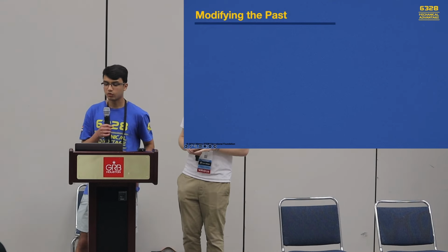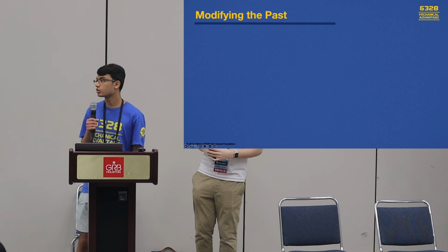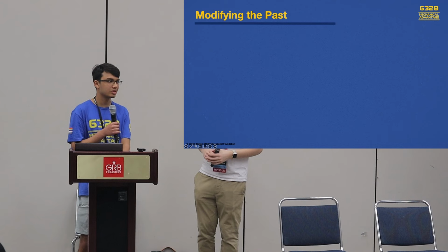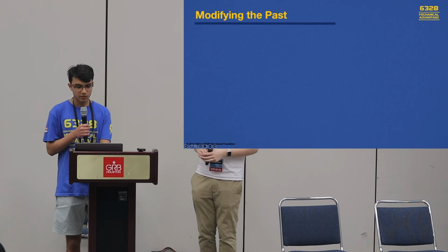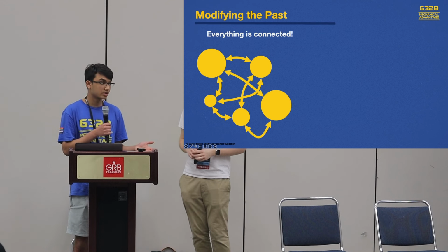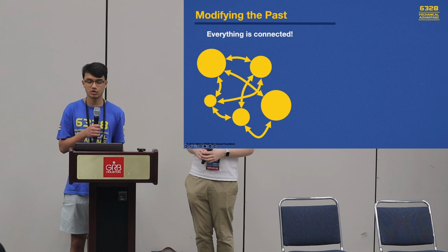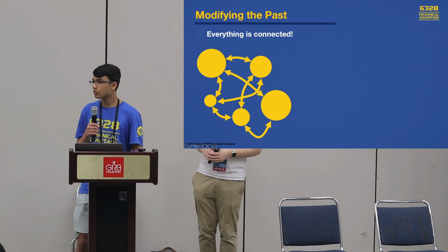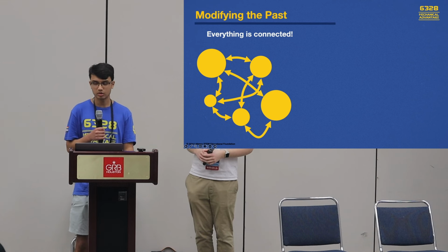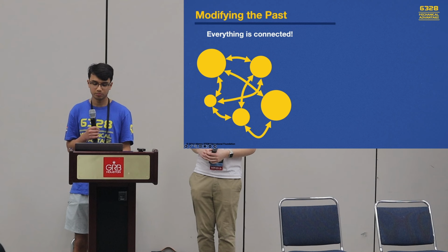All of these examples involve running the same code on the real robot and in replay. This is probably the most common use of AdvantageKit, but you can actually modify the code. There are 2 restrictions to think about when doing this. First is that everything is connected. If you modify one subsystem, it may affect others in unexpected ways. For example, modifying your vision can affect your auto aim, which can then affect your flywheels and so on. This can also cause unexpected match behavior, for example, when you press a single button on your driver controller. Generally, it's best to focus on only modifying one part.